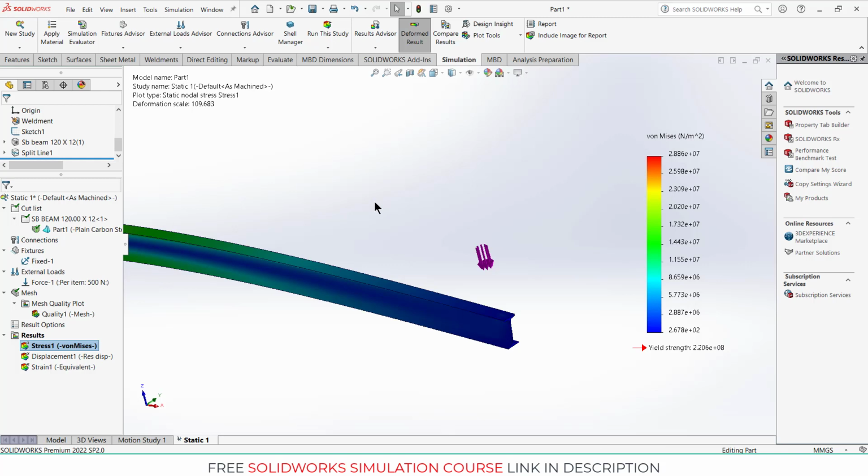For example, if I create a mirror or glass material, and I put a load of 10,000 Newton, we all know it will shatter. Okay, but in SolidWorks it will show bending. As we all know, it will create stress and break. So you need to understand what the data is showing. You are an engineer, so you must know whether it will work or not.